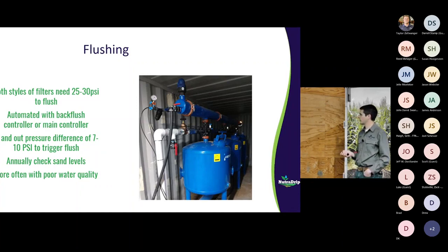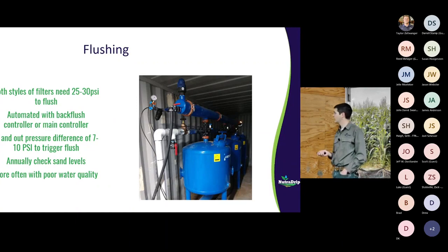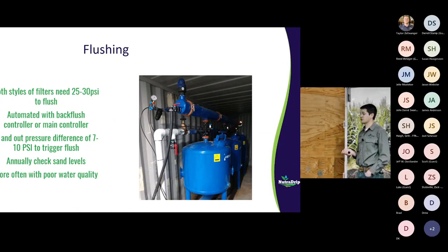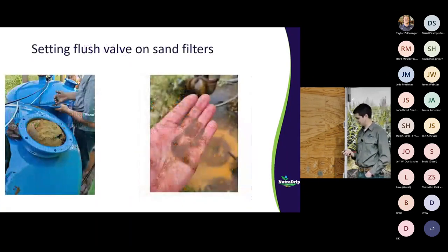This is that brass valve I was talking about that limits how much water is backflushed. We aren't flushing sand out, but it's also important that it's open far enough that it's getting enough of the dirt out, especially if your well's pumping sand.